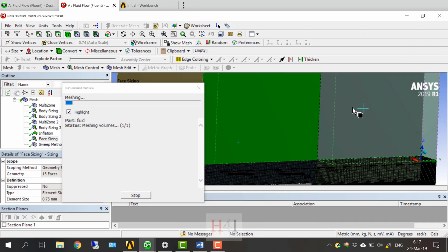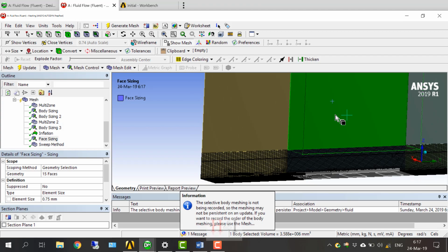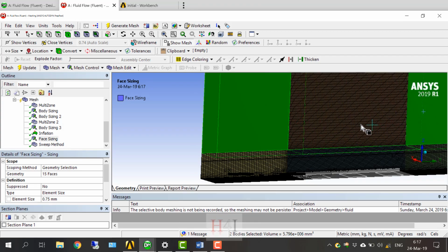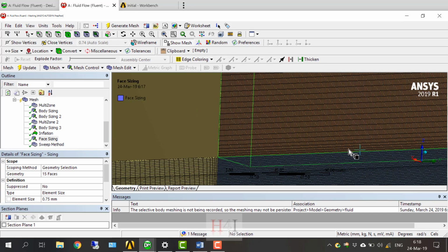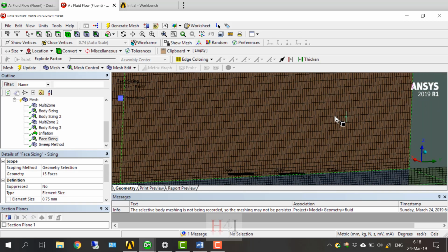Okay, I can create mesh here and here, then here. Or I can create here first. It is better to create a mesh in a sequence: the body, then the body next to it, then the body next to it. Since the mesh is already created here, and here, and here, then I create here, then here, and here. It's like a sequence because each one is dependent on the other. For the third part, the sequence does not matter in this case. Maybe you could try and see, but it's very effective.